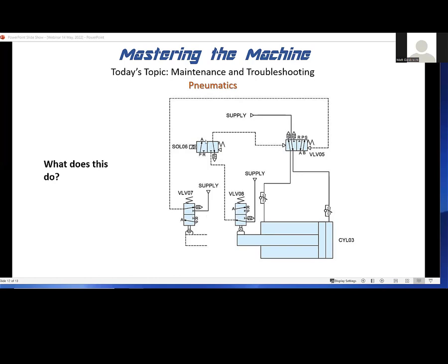And then there's this, which is basically a sort of a toggling system here. And then this is the actual valve that controls the cylinder. So if you read through this, and I give the answer in the back of the book, basically the idea behind this thing is it just toggles back and forth, right? This thing just shifts. It's just a cycling cylinder, but it takes all those valves to do that and to be able to electrically turn it off via this solenoid. So if I turn that cylinder off, then it moves over to this position and it exhausts and it just stays in the same position.